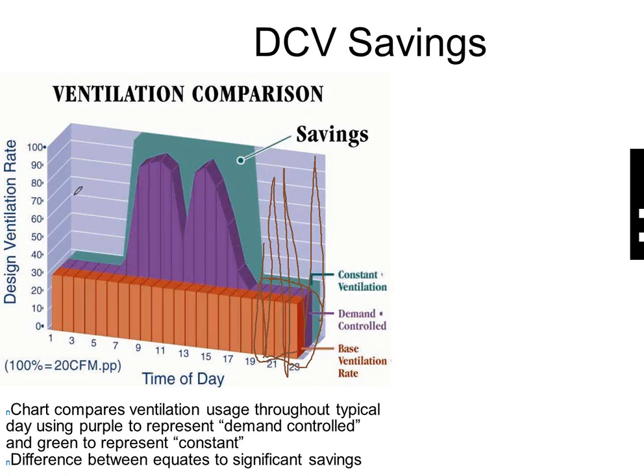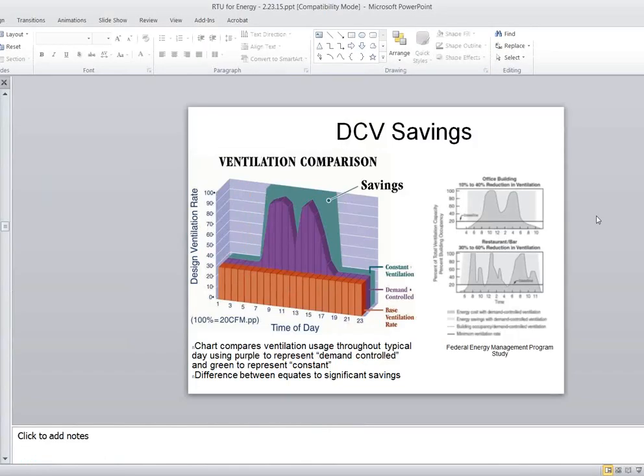Marty also mentions base ventilation rates should address minimum building pressurization requirements. That is true, although I would assume that if the building's unoccupied, in most projects you're also turning off all the exhaust fans and all that kind of stuff as well. And Gary also says the same thing as Marty there, so you guys are on the same page. So usually all that stuff can be shut off completely, but if you are running exhaust in the nighttime, then you would have to also deal with that.